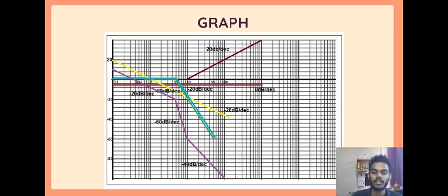Now this is the graph we get from the magnitude Bode plot for the transfer function we just analyzed. Starting at low frequency, the plot begins at around negative 8 dB, which is due to the constant gain term, 20 log 10 times 0.4, we discussed earlier. At omega equals 1, the zero starts to take effect and introduces a positive slope of 20 dB per decade.